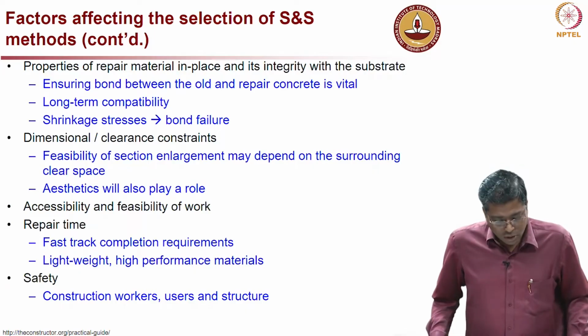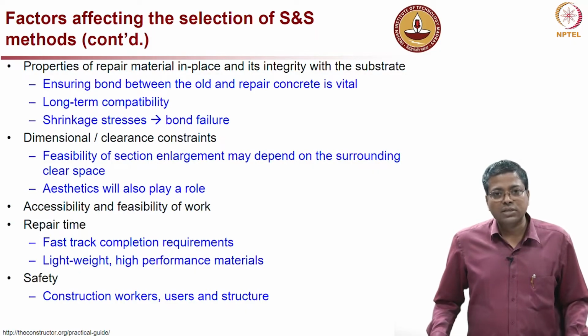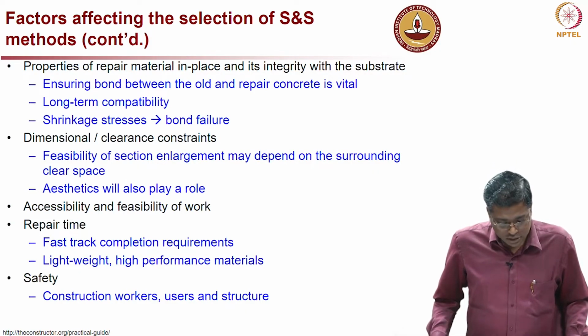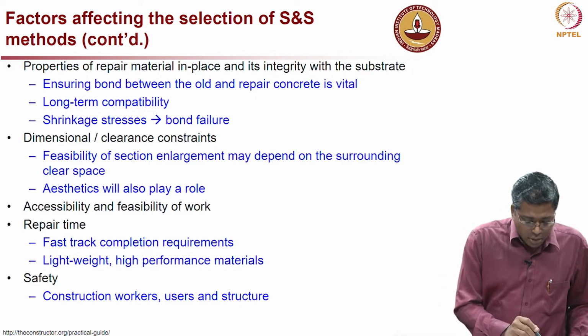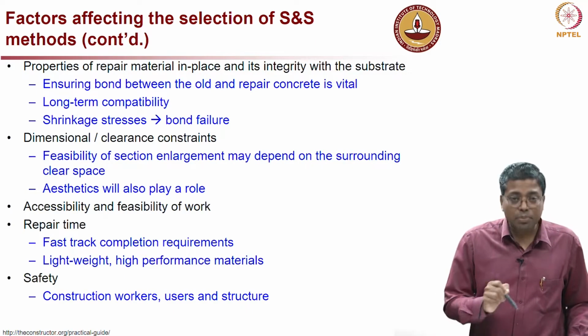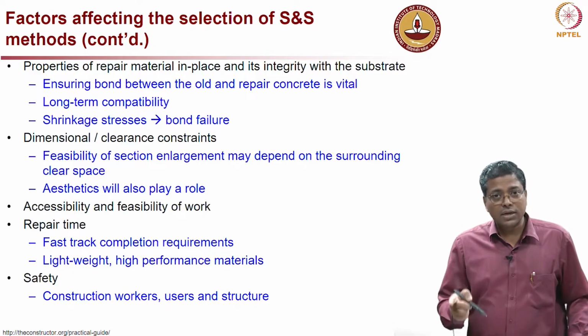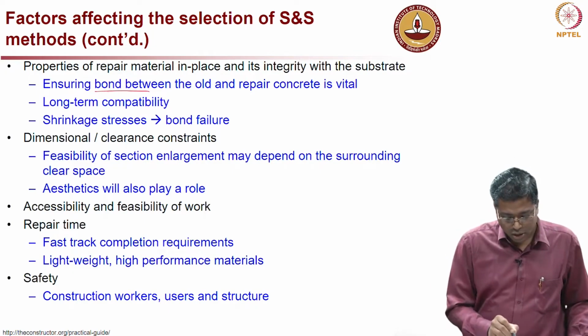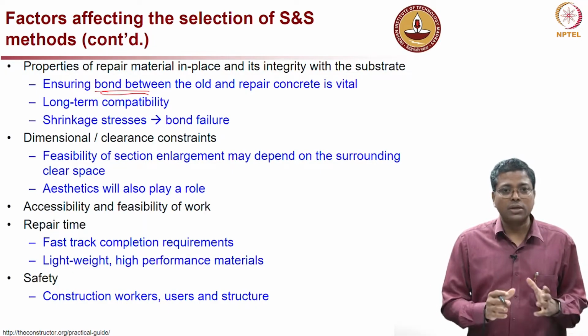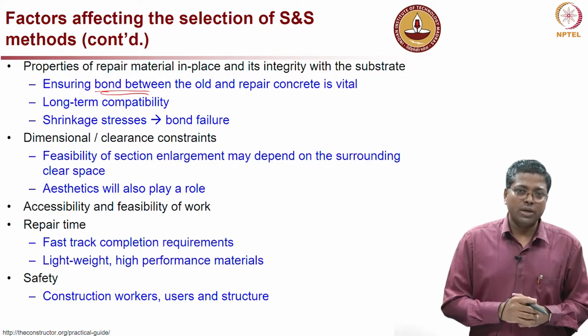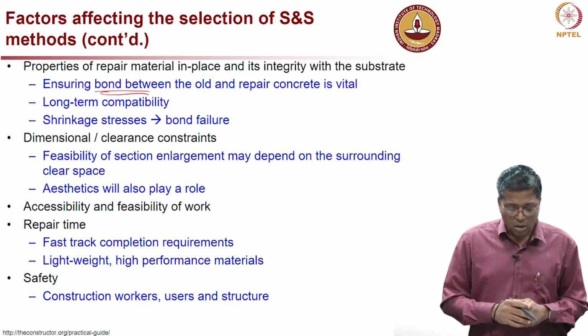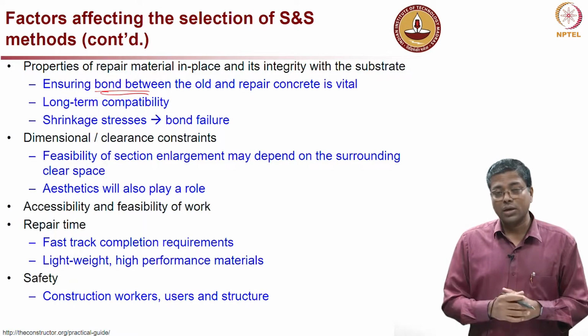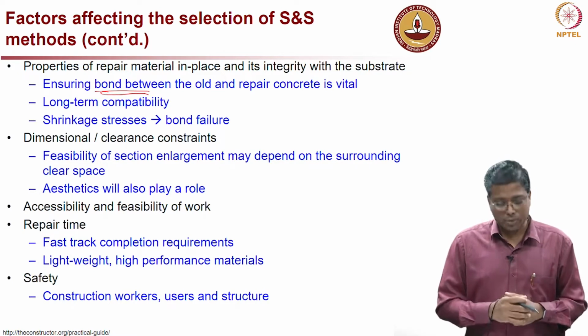investment. Now, more factors which affect the selection of stabilization and strengthening techniques: properties of the repair material in place and its integrity with the substrate. The bond is very important. How compatible is this repair material with the existing or the substrate material?